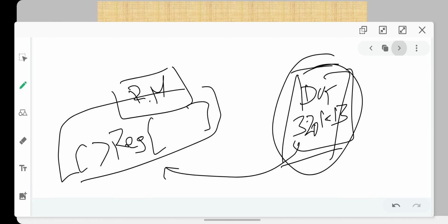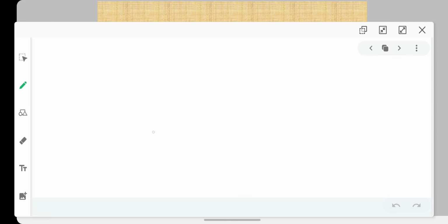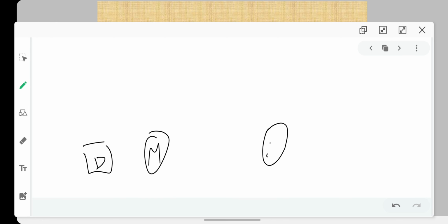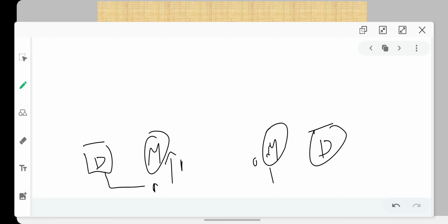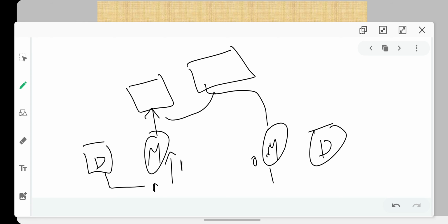For example, you have the first monitor, the driver, and the second monitor. You're driving a value of 1. Your monitor has monitored the same value 1, but your output for this 1 is going to be 0, and your monitor has monitored that 0. Now the driven value is given to your reference model and the scoreboard. I mean from the driver, sorry, not from the monitor.